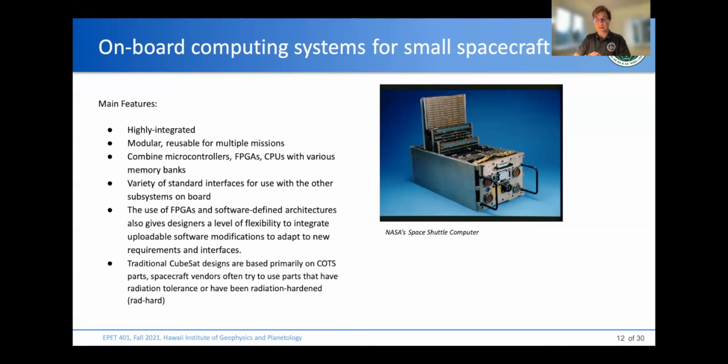It used to happen that many flight computers were developed using non-COTS parts, so basically everything from scratch, and of course that becomes extremely expensive to develop. But the advantage would be that you could design exactly how protected your hardware is from radiation, and you have increased reliability.